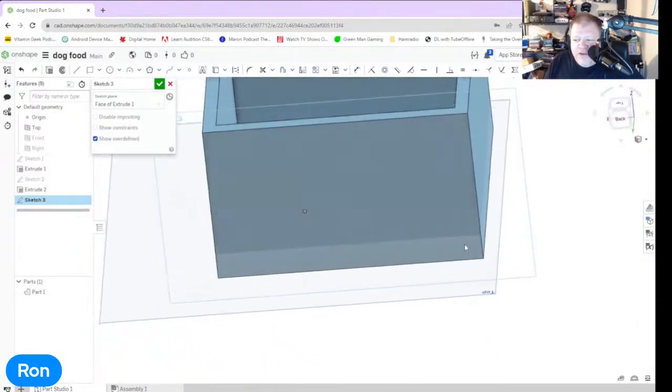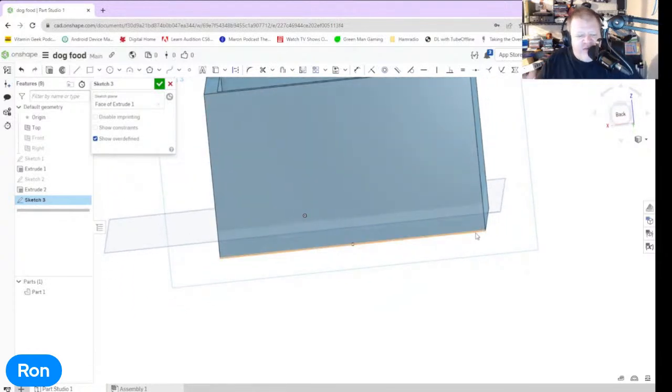So what I want to do is I don't want to cut right through that 5 millimeters on either side. So what I'm going to do is I'm going to build a box around a box. The first box we're going to build is going to be a construction box. So down from the plane, come across here, and come up. That's my construction line. We're going to use the construction line to make constraints. You can do this with construction lines too. Something you guys may not know.